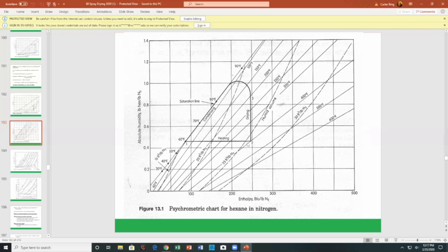So we have the heating going on, then we have the drying operation. Now then, since it's hexane, we want to have a condenser, and the condenser will condense out the hexane back to the original starting conditions. So we pull hexane off as a liquid. Coffee will come on out. Instant coffee will come out as a solids flow, not showing here. But I'm just saying that these types of psychrometric charts are available for all kinds of different stuff.